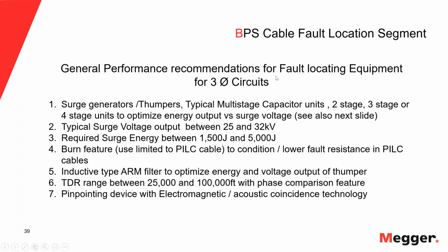And that fault will be afterwards, you will not be able to thump it anymore. So it's a totally different issue when I have paper cable, because in paper cable I have oil in it, and I need to lower the fault resistance so I can thump it. And that means I have to burn the oil, literally burn the oil and make carbon from the oil. So I have no carbon, and carbon has a lower resistance, so I can thump the fault.